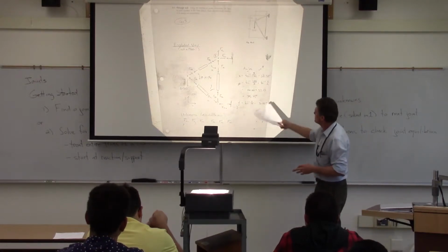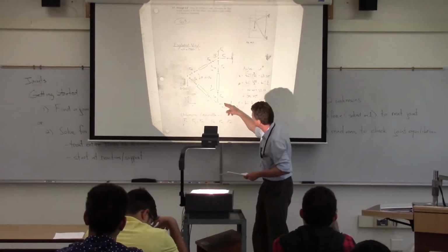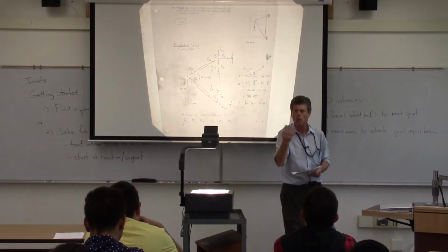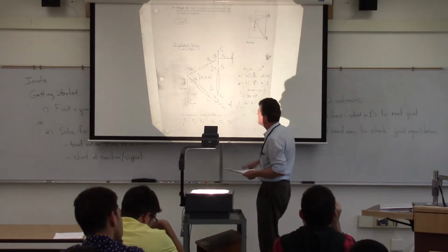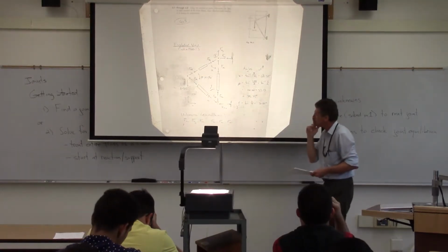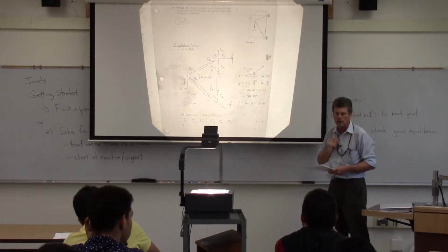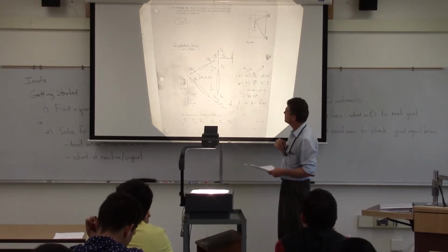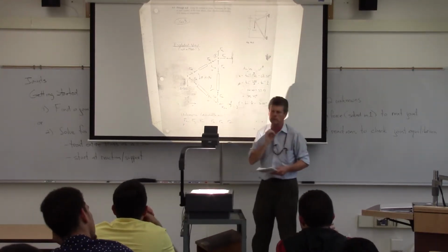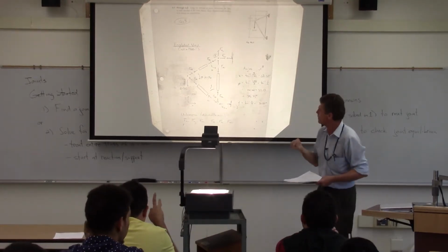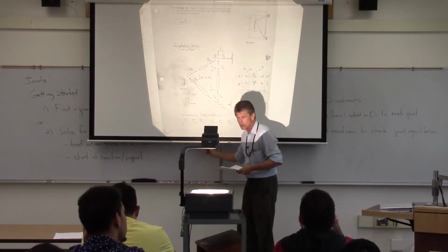And then these are, again, just a bunch of angles that are calculated there because they didn't give you any angles there. But again, when we think about this, what we're going to want to do is when we get into that joint equilibrium, we're going to want to solve forces in the x and the y direction, set them equal to 0, and then solve for those components. So our unknowns in this particular case here are going to be the three support forces there, and then the three member forces. And what we'll find is that's 6. We have 1, 2, 3 joints. Each of those joints has 2 equilibrium equations available to us, basically, so we'll be able to solve for all of them. Any questions before I hide this?